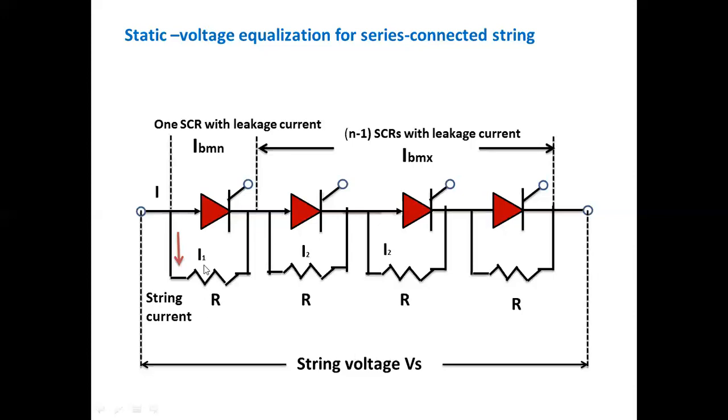When we get the voltage drop across each SCR, it should be 10 volts V1, 10 volts, and so on; there is no problem. That is an equal voltage distribution. But in unequal voltage distribution the voltage levels change: here we get 9, here 11, here 11, again 9. This 1 volt or 2 volt difference is called unequal voltage distribution.